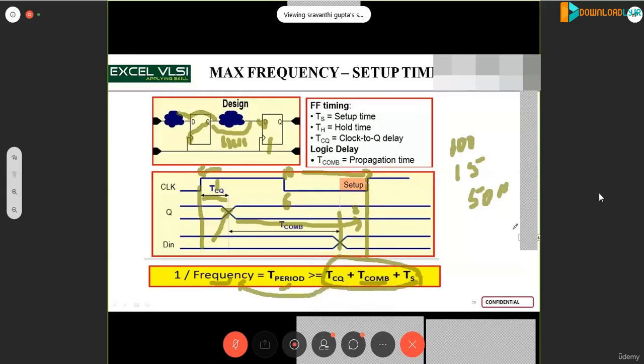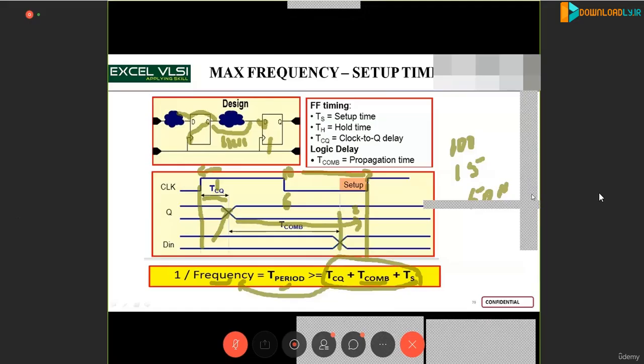So this is the base of it, and basic for all this. Shravanti will take you through more in the static timing analysis. That is the intent. She's not spending much time here, so just the basics. So it is governed by this, the synchronous circuit timing analysis. Hope you understood. So now this is setup, and then here T hold is the minimum time the data has to hold after the edge of the clock, right? And so further it goes on. We will learn more in STA. Because the slide was put, and for some of you beginners, I thought let me explain.